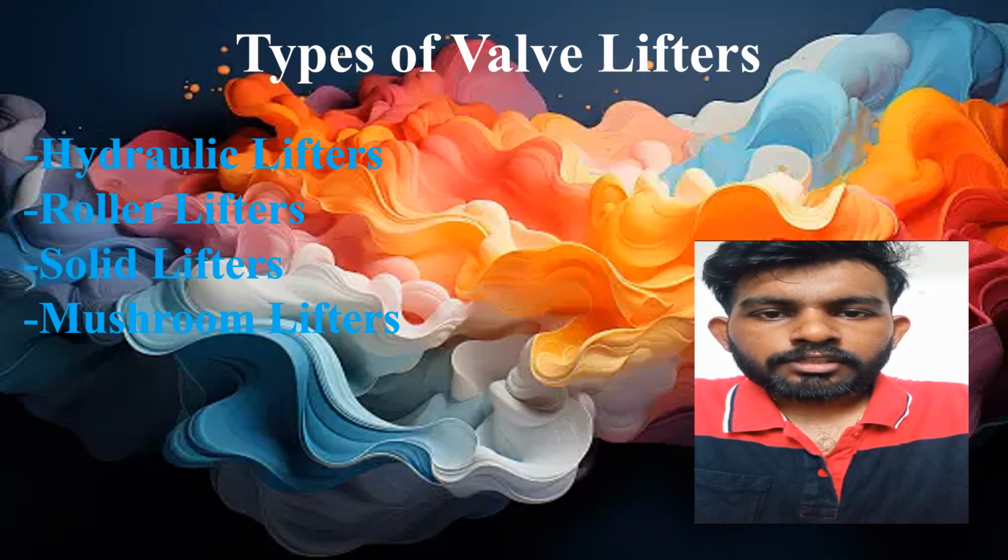The second one is roller lifter. Roller lifters are similar in design to hydraulic or solid lifters but feature a roller wheel at the bottom of the plunger. The roller reduces friction between the lifter and the camshaft, resulting in smoother operation and reduced wear.